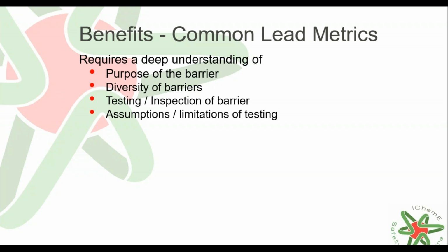Those things come out of understanding the barriers and the lack of diversity you've got on them, because what you become exposed to very quickly is the fact that you're putting a lot of weight on those barriers, and obviously a closed valve at the back end of a PSV completely defeats all the purpose we talked about for 10 minutes on PSVs. So making sure that you understand that correctly, respect it and look after it is pretty important.